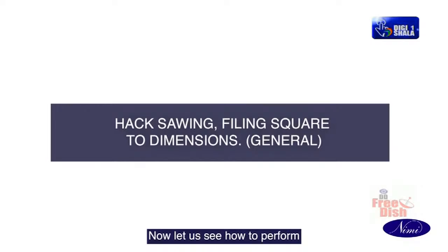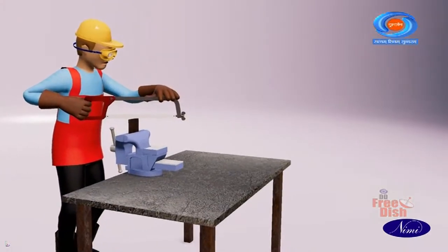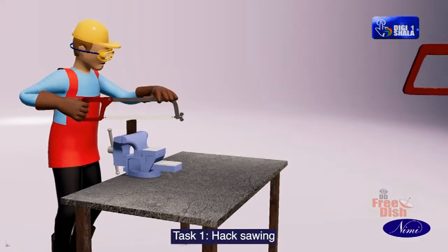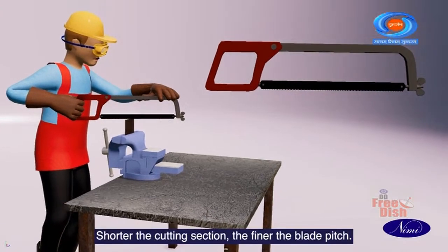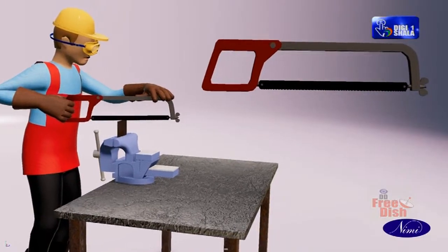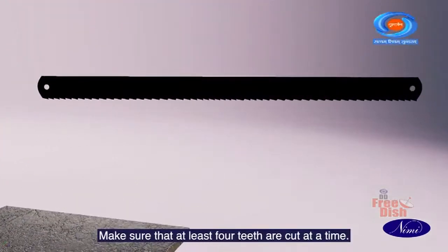Now let us see how to perform filing and to maintain square dimensions. Task 1. Hacksawing. Select the correct pitch blade for cutting. Shorter the cutting section, the finer the blade pitch. Make sure that at least 4 teeth are cut at a time.